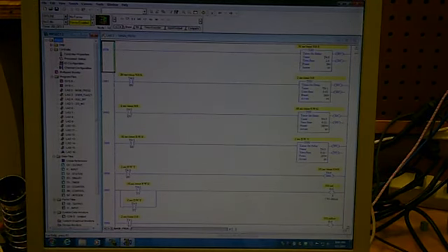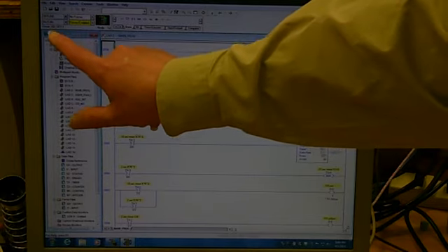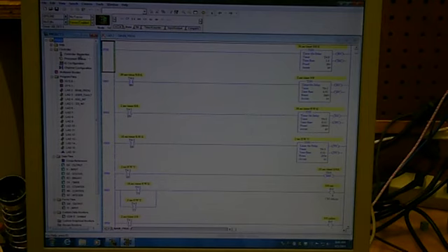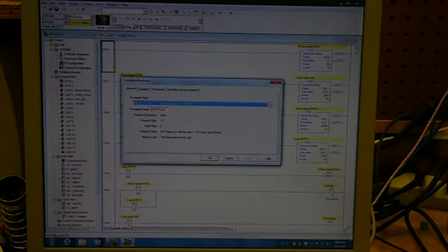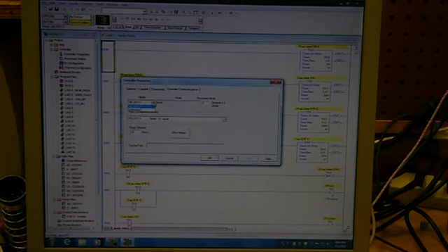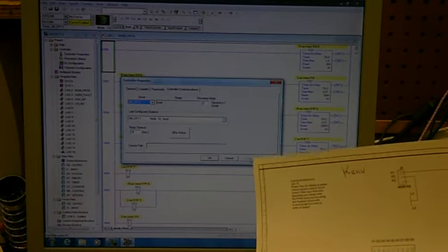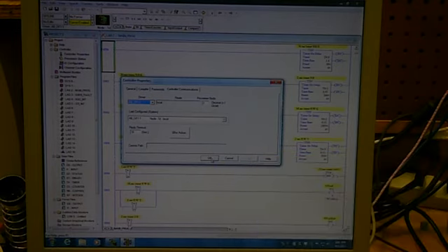We're going to make sure, we notice that our driver is a DF1 driver, and we're node 1. The DF1 driver is always node 1. Go to controller properties. If you don't have controller communications, if you don't have the right driver there, then that's where you would go get it. There is an apply button there. When Allen-Bradley gives you an apply and an OK, always hit the apply button first. It's supposed to be node 1. If it's not, you won't be able to talk to it. Say OK.